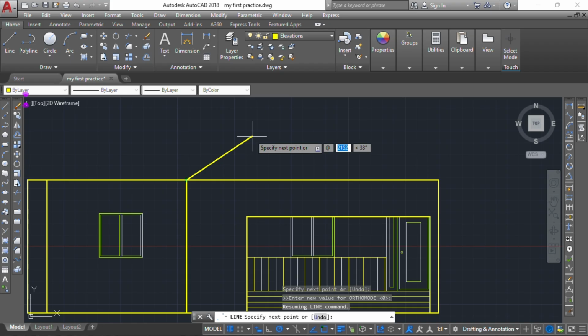Now the first one is your distance, right? Let's assume 1500, just an assumption. It will be edited later. And now for you to move on and give it the bearing, press Shift and the lesser than sign on your keyboard. And now let's give it the angle of 22 degrees, right? And enter. So we are having this, right?